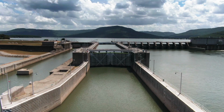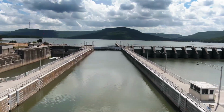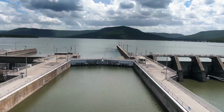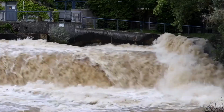These extreme floods are often determined through hydrology. So how do we determine the extreme floods? We make sure we determine the design flood. The first step in spillway design is estimating the design flood that the dam must safely pass. For many dams, engineers use the probable maximum flood, often abbreviated as PMF. The PMF represents the largest flood that could physically occur in a watershed.